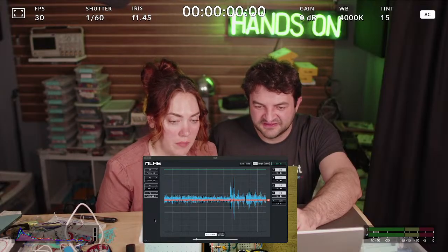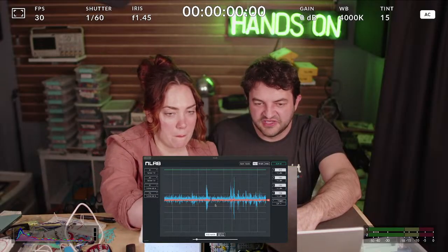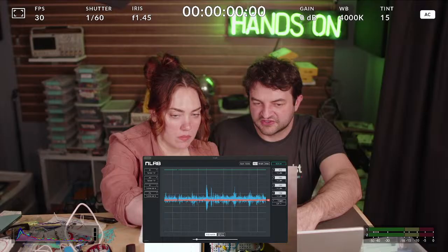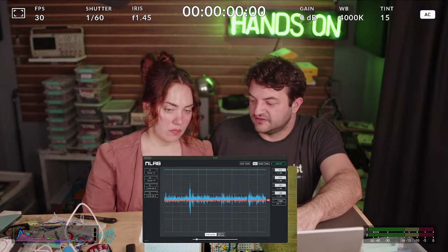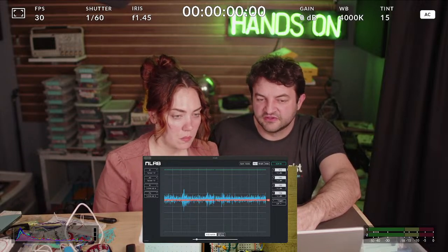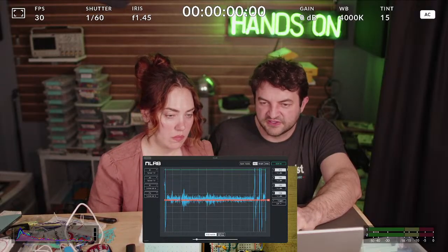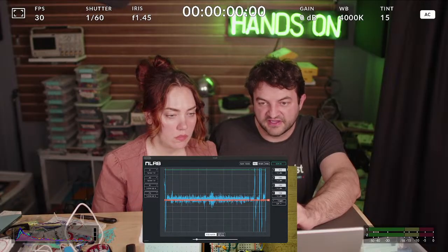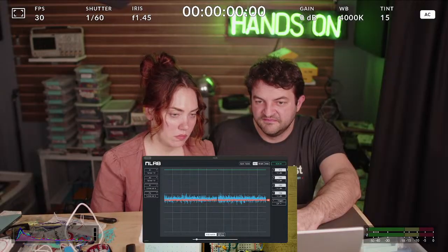Are all capacitors directional? That's a good question. No, typically only electrolytic capacitors are directional, not the little normal sized ceramic ones. The big ones, when you see something like 1,000 microfarads, usually come in a cylinder and are usually blue. Those are directional. Usually you can tell because one leg is longer than the other, or the body has a little stripe on the side. That's the minus side. It's literally the minus sign.